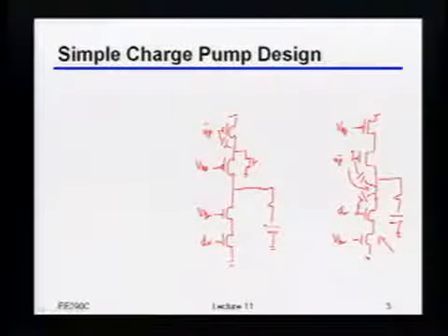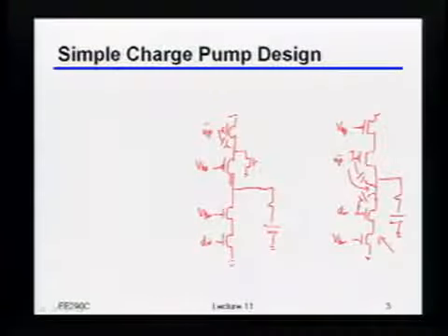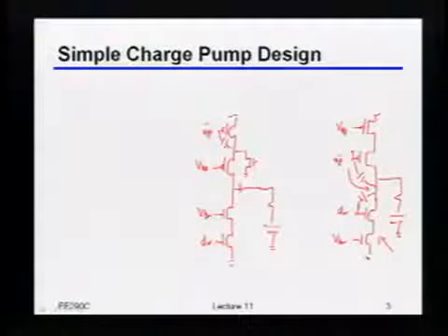Now, this is not entirely for free, because if you do this, you just have to make sure that the charge pump output voltage over here never gets close to VBP, or really never too much higher than VBP, because if it does, then obviously the switch turns over and bad things happen, right? But as long as you have a reasonably small range at the output, which we'll come back to in a second, then you could try and play some game like this.